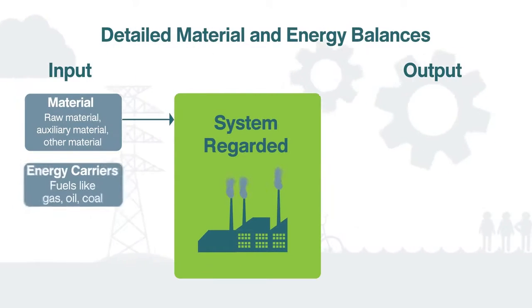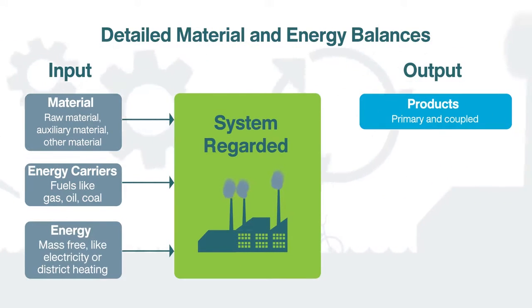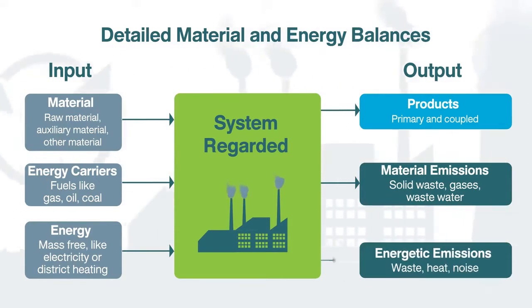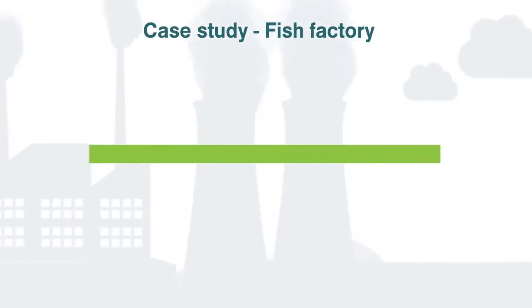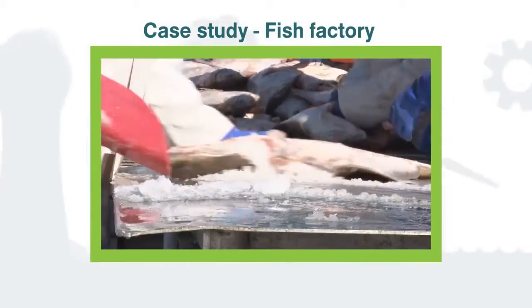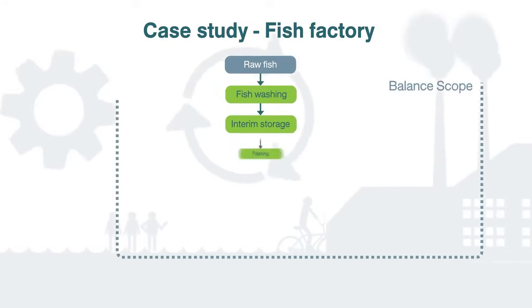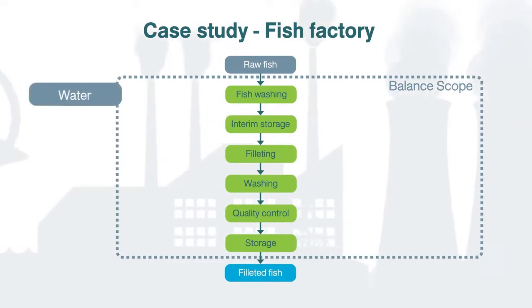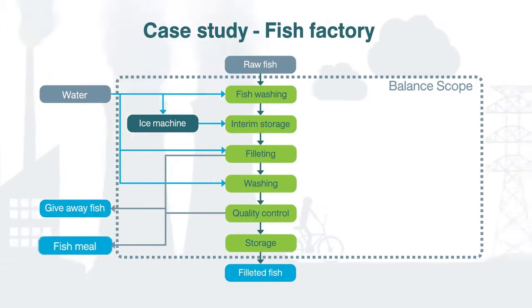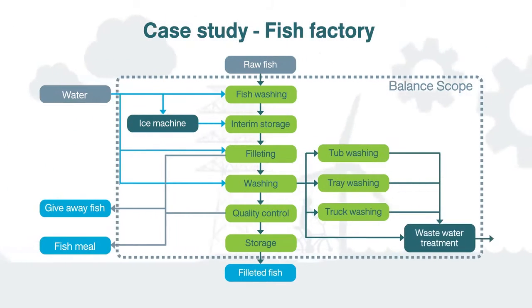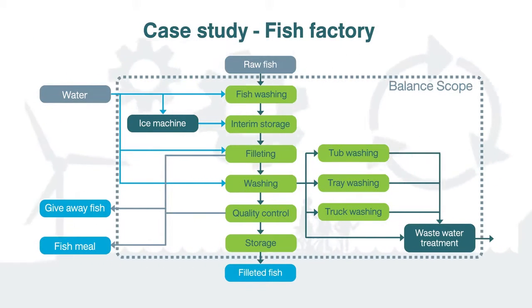On completion of a material balance, the user will have a process map of all the input and output material flows and their quantities. This then allows the user to assess where losses and excessive flows occur and to strategize around the implementation of an appropriate intervention program.